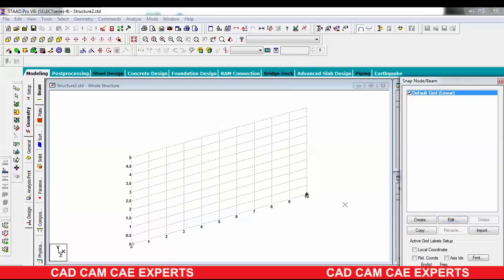Okay. Now make a node at 0 and hit your control button, and as my height is for one way 1.5 and the second will be at 3, go for that, and my length is 2 meters, so make a node at 1.5 and release your control button.